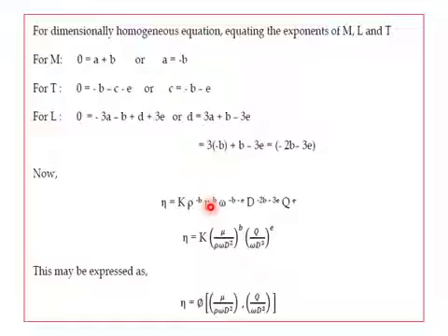So mu divided by rho omega D square. So minus 2, it's D square. So similarly we are expressing in terms of like power e, which is Q divided by omega D to the power of minus 3, that is omega D cubed. So now we got this as one dimensionless term, and this is also another dimensionless term. Hence this dimensionless term can be expressed in terms of this and this. So that's why it is written as a function of mu by rho omega D square and Q by omega D cubed. So that is the expression that we require.